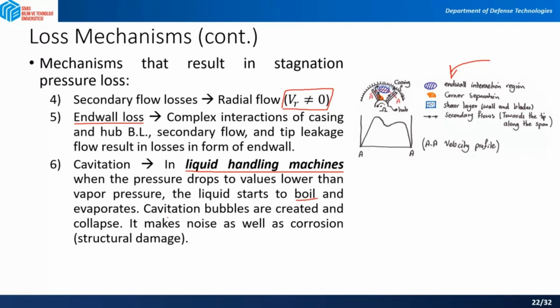And while evaporating, you know that the cavitation bubbles are created and then collapse. When these bubbles inside the liquid collapse, they make noises, and also they make corrosion, and it means that you have structural damage on your blades as well.